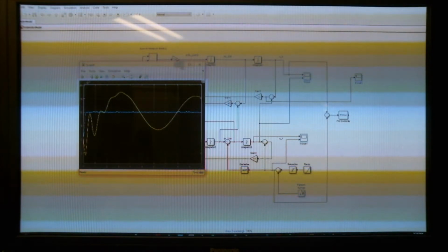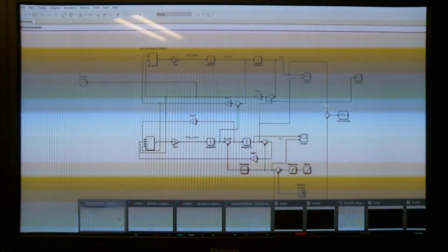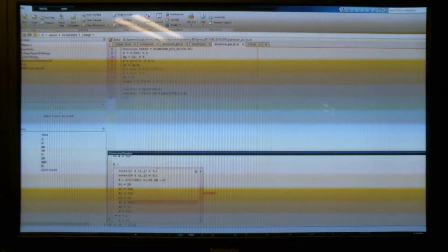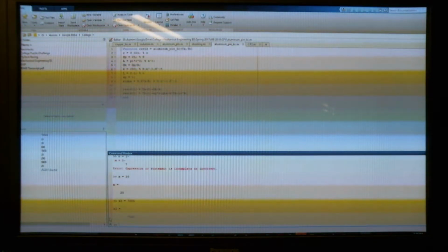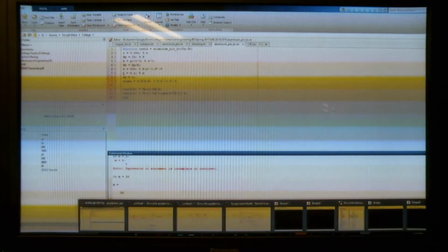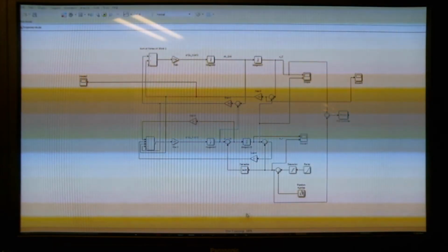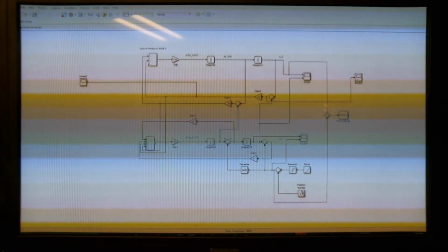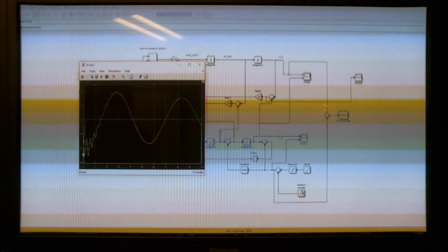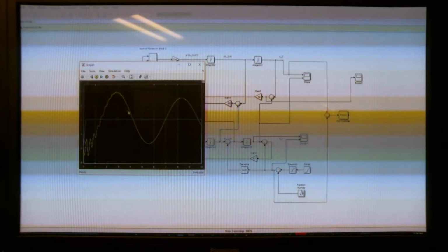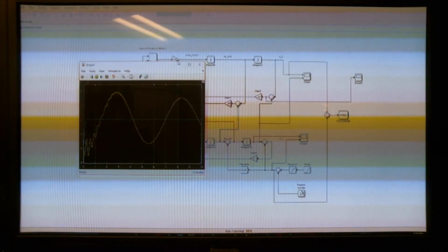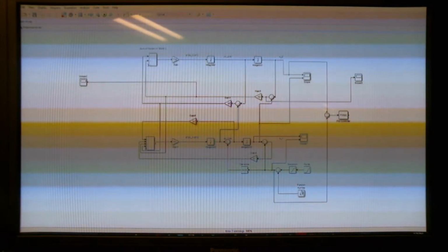By changing your parameters in MATLAB, you can view different response characteristics by changing, let's say, the spring rate of one of our springs. We can buy either a stiffer tire or a stiffer spring and then rerun the simulation to see what that does. We can see that it moves the early response down a bit, but it still causes steady state oscillations. So you can damp those.